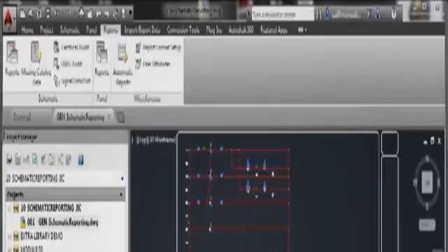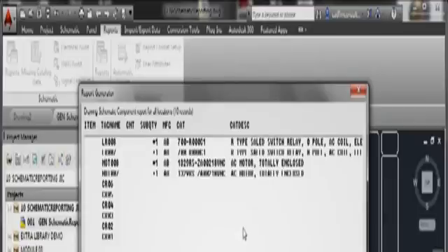We're going to go for components on the active drawing, category, schematic, options. We'll tick all of them, including children for the parent-sibling relationships between any components on the drawing. We'll also freshen the project database to make sure that the data in the report is up to date. Installation codes, we'll have all of them. Location codes, we'll have all of them as well. So when I click on OK, it generates our report like so.